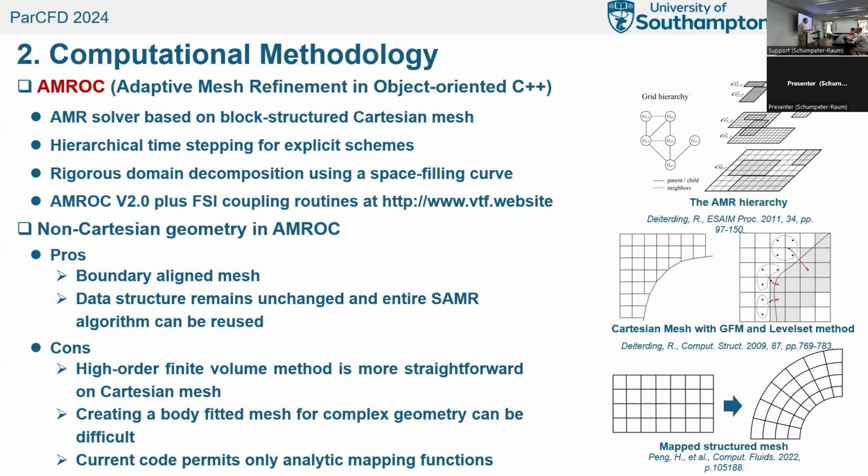So the original version of MROC, also published a while ago, was using embedded boundary methods based on level set, so purely Cartesian techniques. However, here we are dealing with non-premixed combustion. We have to deal also potentially with boundary layers. If you imagine an annular combustion chamber with Cartesian grids, that would be quite some numerical accuracy loss that we would be encountering at the boundaries.